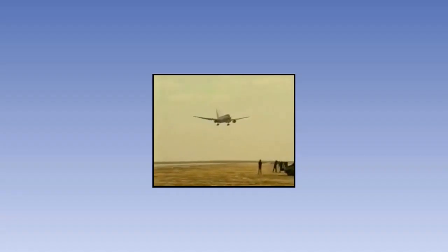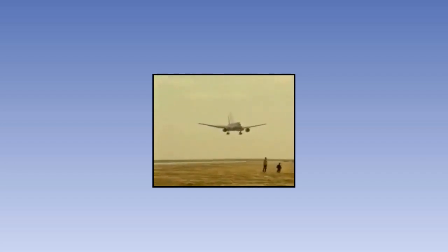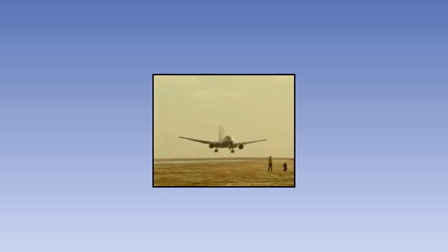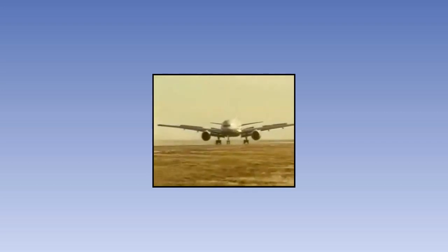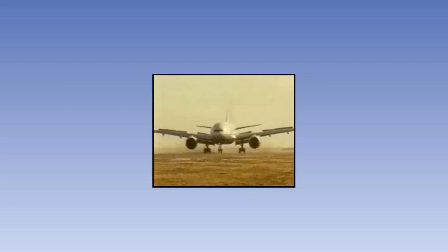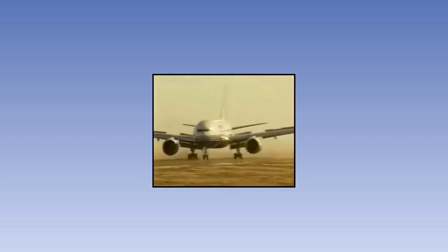An important note is that there is no allowance for crosswinds, and therefore no safety factor for crosswinds. Crosswinds present an additional complication because of the effect of potentially crossed controls, which would have to be applied because the wind will tend to push the aeroplane off the centre line. These issues mean that aeroplanes are given maximum crosswind limits.